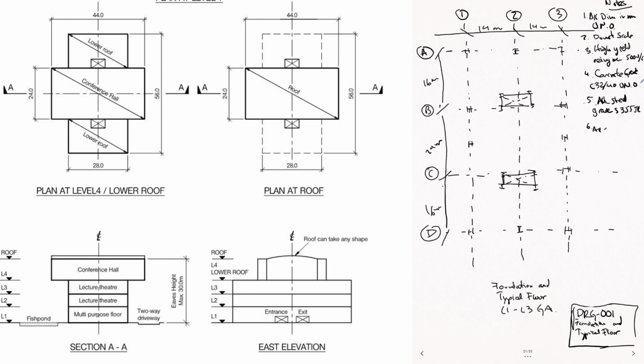Make sure that you write all the notes in a single drawing, normally the first drawing that you do, and then all the other drawings that you do afterwards just make reference back to this drawing. So, for example, here I'm writing typical notes that you will have in a concrete structure. I had a template of the notes for different types of structures, and then I just write, this is this type of structure, and then of course personalize it, amend it, and make sure that everything that you need is included in there. Make sure that you include all the reinforcement estimates and also a schedule of beams and columns.